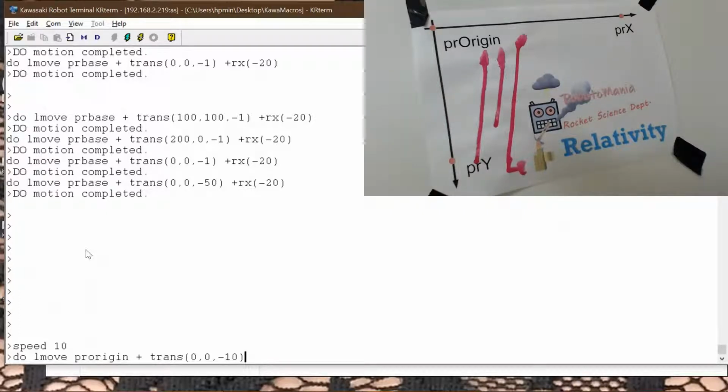Now, you have to understand that this kind of vector geometry always works in the tool coordinates. So if this point is reached by the robot and the hand has a certain orientation in space in a certain position, the next operation will depart in the tool coordinate system of that point.